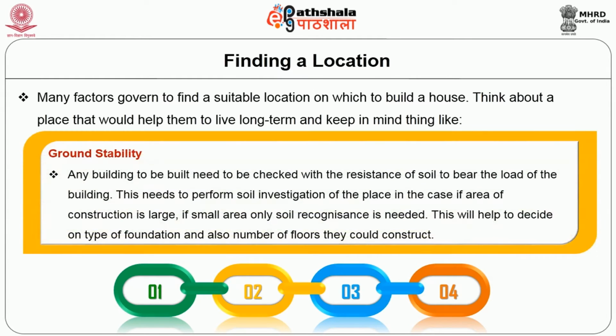Ground suitability. Any building to be built needs to be checked for the resistance of the soil to bear the load of the building. This needs soil investigation of the place if the area of construction is large. If small, only soil reconnaissance is needed. This will help to decide on the type of foundation and also the number of floors they could construct.